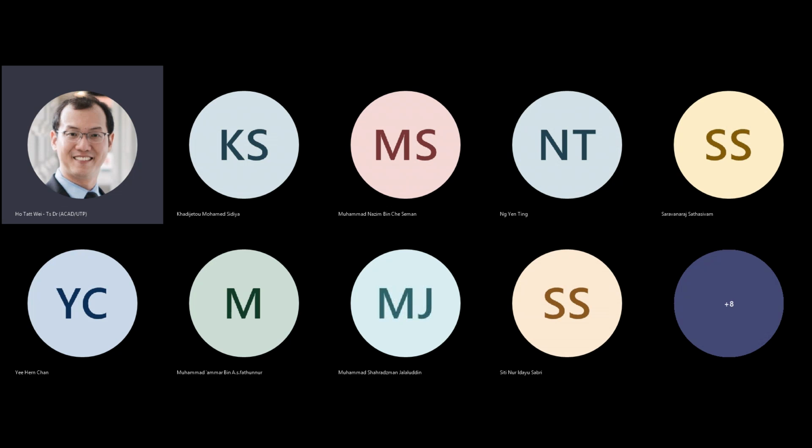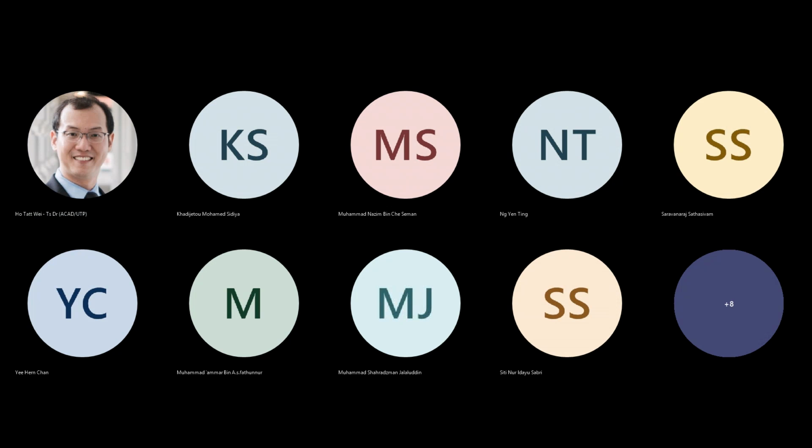And it's important for us to understand two relationships. That is the relationship of the current as a function of voltage, for example VGS, that is the voltage put in at the gate, and the relationship of the capacitance as a function of, again, VGS, VDS.